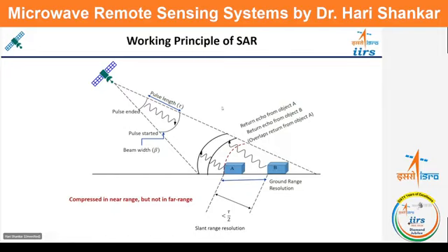And this is called the beam width. The beam width is along the range direction as well as along the azimuth direction. We will see the relationship between how much beam width we should keep, what the antenna length should be, and which types of radiation can give better resolutions. The resolution depends upon different satellite parameters, or antenna parameters, like the beam width, antenna length, and directivity.